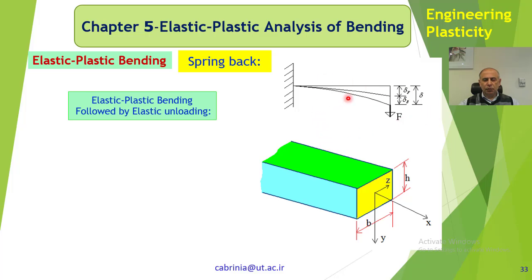But if we increase F greater than the yield point, so that the bending moment stress which is applied here is greater than the yield stress or yield strength, then it will deform plastically. It depends how much we increase F over the yield point. And what happens is that when you release the load, if you take off the load from the beam,